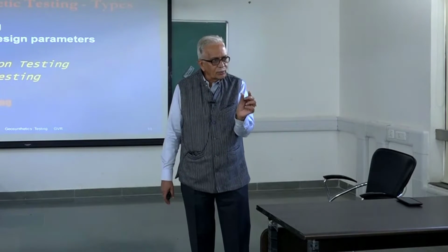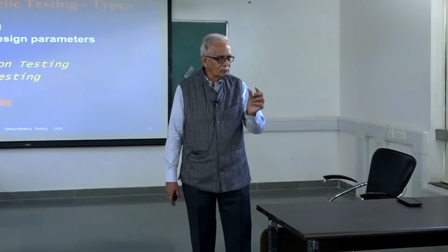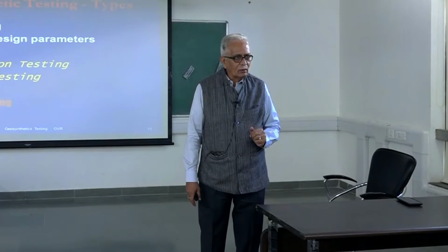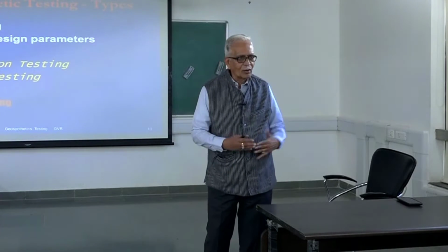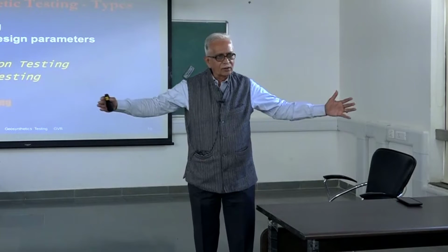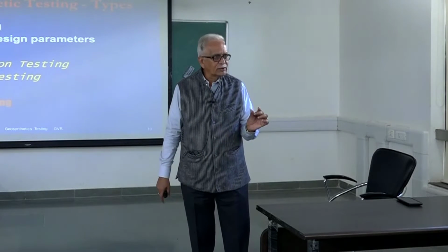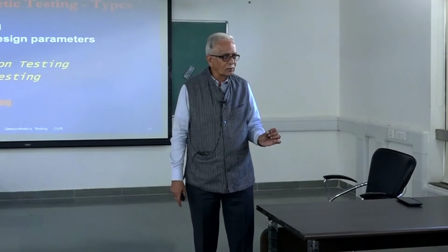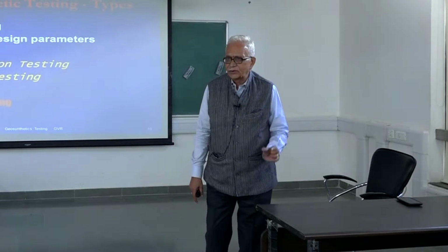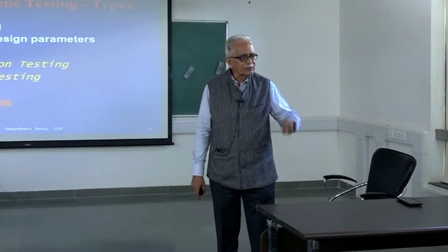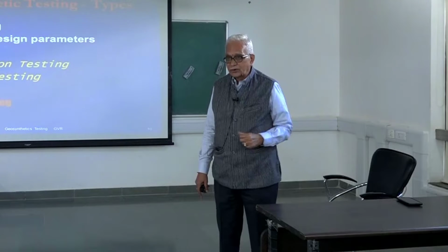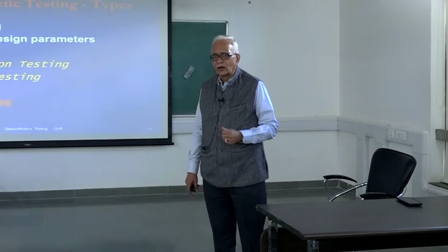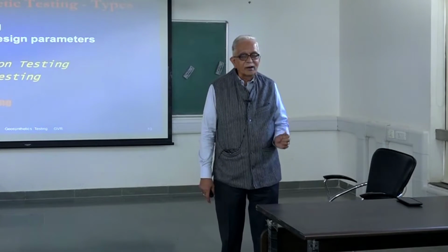So they were used to doing tests on very small size specimens, and in those days probably the width of the roll also was less. But now that we are using very large widths, testing small pieces like this may not be effective. And also they were doing the testing at a very high speed. I told you quality in the production is very important. So the test itself was done at the rate of 300 millimeter per minute.